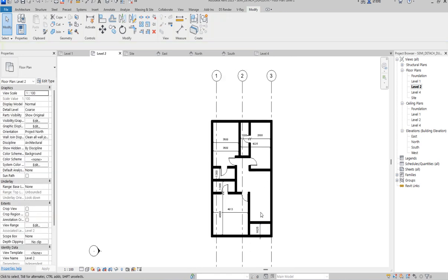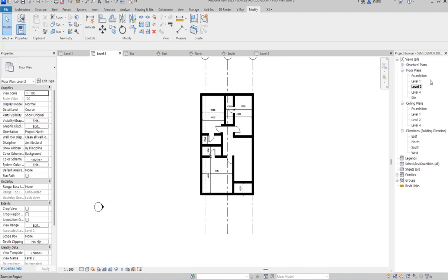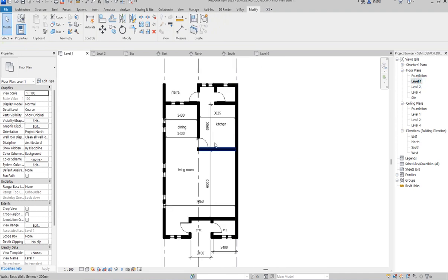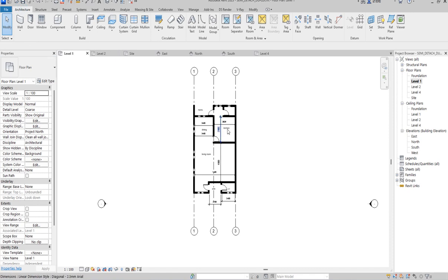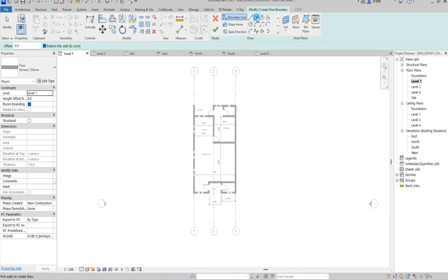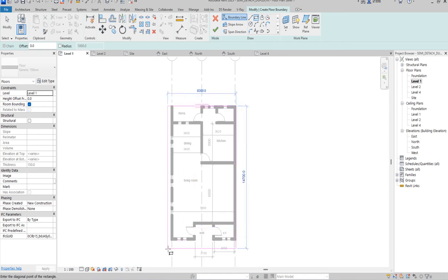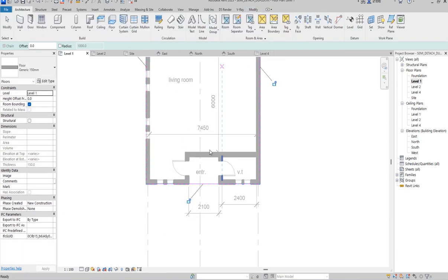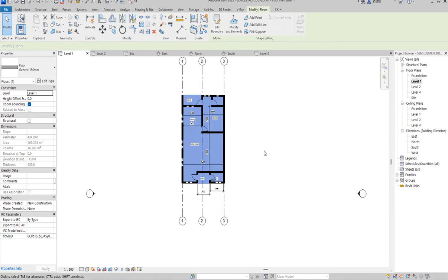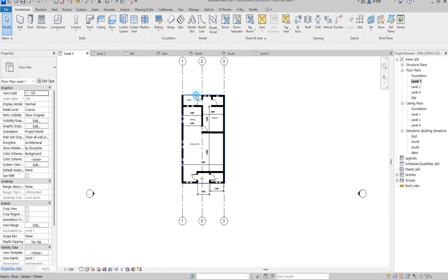So this is the stair where they need to climb and do all those things. So I have done this one. Now I quickly need to do one thing. I want to create a floor here. So I will just click and say this is how you create a floor. You come to Floor on the Architecture tab and click Architectural Floor. You select rectangular, which is okay for now. If there's any other need for editing, you can do that in future. So you've done this one.